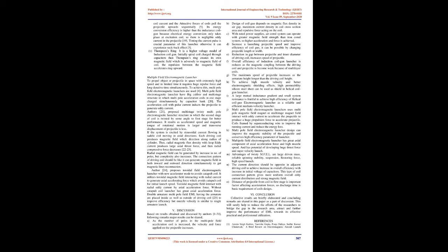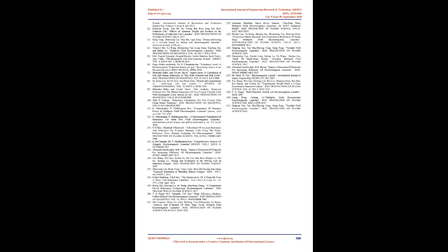3. Reconnection coil gun launcher. This coil gun type has a disc-like shape. The acceleration coil is made of two coaxial copper coils and the projectile is plate-shaped, located in the gap between the two accelerating coils. The external coil produces a time-varying magnetic field which induces current in a conducting plate. A current is pulsed through the coil and produces eddy current which propels the projectile. It works on the principle of a reluctance motor.